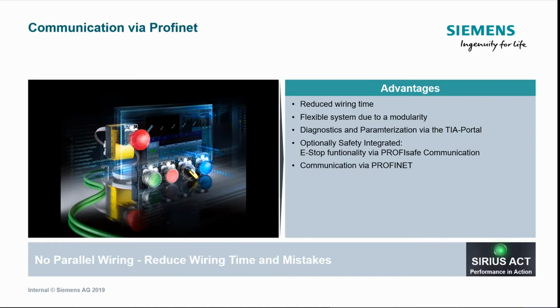You can only put the e-stop on the safety version, and you can't put it further down the line, but it's really easy. Again, it's been designed to be nice and simple to install. Again, no special tools needed. You install your devices, and then you cut the ribbon cable down to the desired length when you're daisy chaining off the interface module.